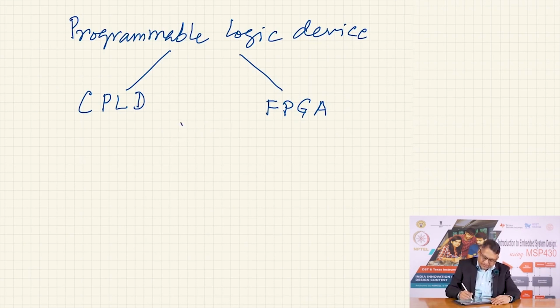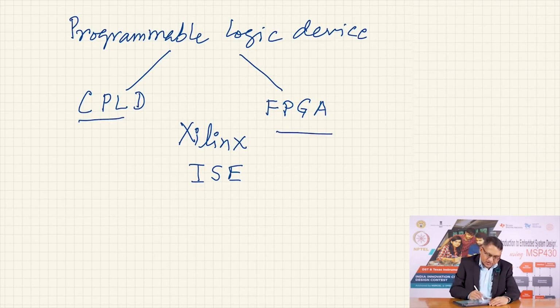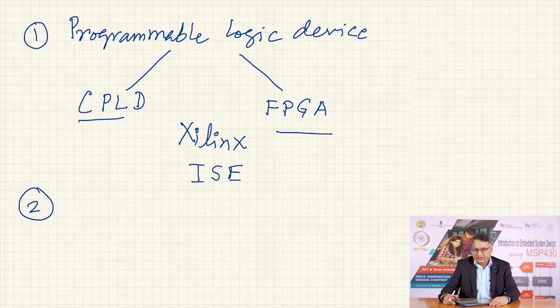They have a software called ISE, which allows you to write, test, compile and download the VHDL code or Verilog code into the target IC, which could be a CPLD or FPGA. So, this is one approach. The second approach could be that given the netlist, you can get an application specific integrated circuit being made. That is another possibility.